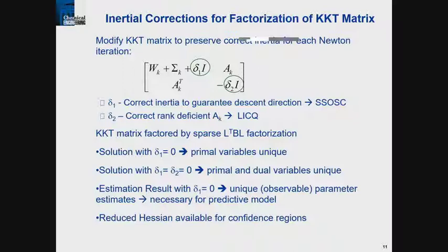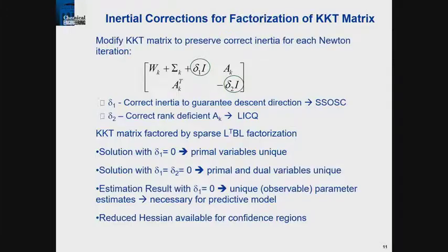Now, this is essential because the model that we want to develop is predictive, extrapolative, right? So if you have non-unique parameters, that's not going to work. If you have non-unique parameters that lie in some subspace, then those parameters really don't mean very much. They have huge confidence regions, well, infinite confidence regions, that mean you really can't trust that model to predict things. So this is an important thing that we look for when we do parameter estimation.